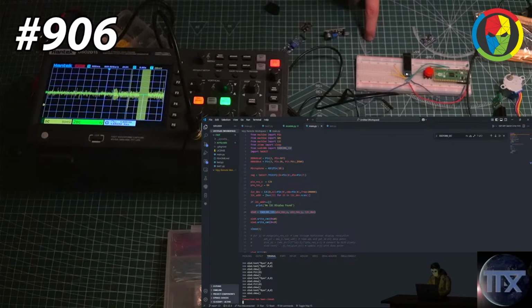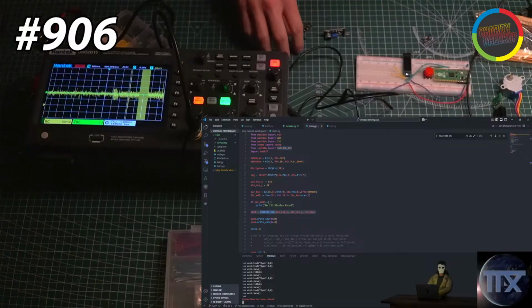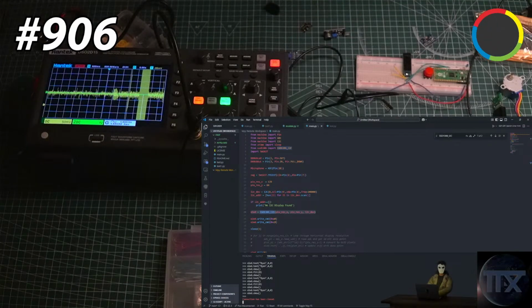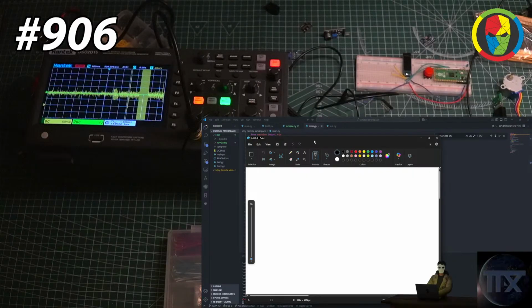No, ground to ground on the 3 pins. So 2 wires are connected to the power supply, but the ground of the probe of the oscilloscope will also be connected to the ground of the power supply. And then you put the signal on the signal line. Hold on. Does that make sense? Let me maybe draw it out, because that'll be much easier.